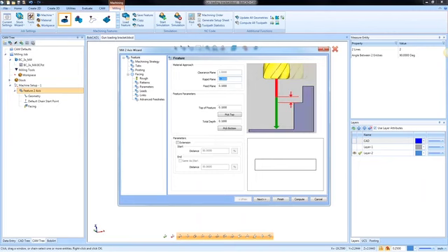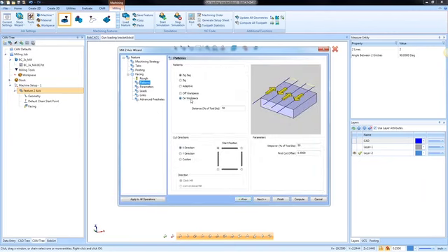When you have it set to off the workpiece, okay, so right now I have it on the workpiece, 50% of the cutter. If I say 0, it will go off the workpiece, really. And then if I say 25%, 25% of the cutter will be on the workpiece. All right. Same thing with off. This is the distance. So it's pretty straightforward. I recommend that you kind of go through it a couple of times, adjust some of the settings and see the result. And that's really a good way to kind of get familiar with it here.